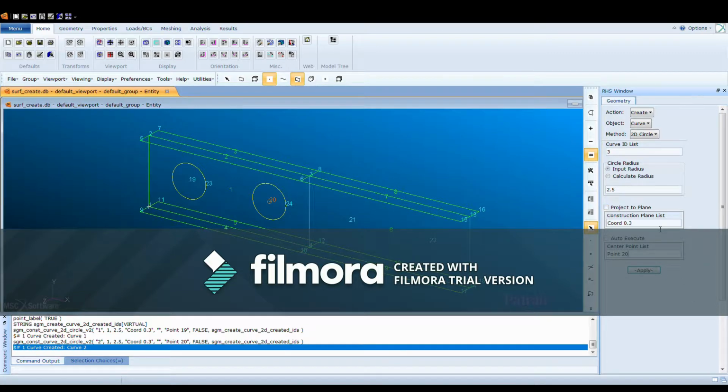Now we're going to extend the parametric surfaces, which are our green surfaces, and for that we go to edit geometry under the surface object, and our method is going to be extend. So we're going to select the fixed length icon and select edit all associated surfaces, which is our first option. Already set. Our length is going to be set to 2.